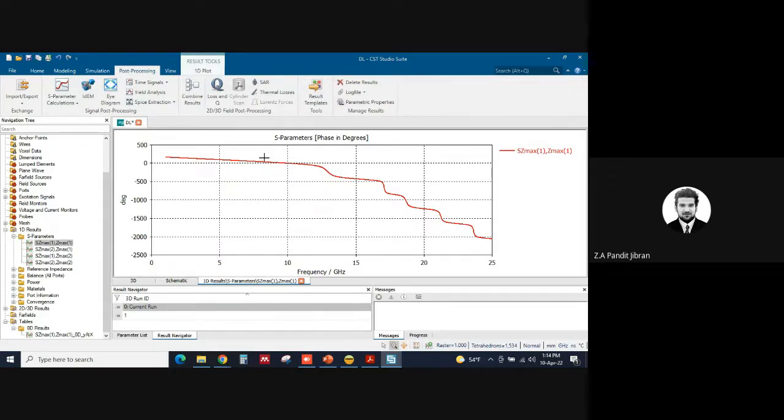We make it from zero, right? Yes. No, not from zero. See, the whole operating frequency range, what is the phase I am getting? That's all. See, while designing a metasurface, you will see there are two curves. One is phase versus loop length, or some geometry length. The other is location versus phase. What phase is to be compensated at each location of the reflective surface, or whatever it may be.